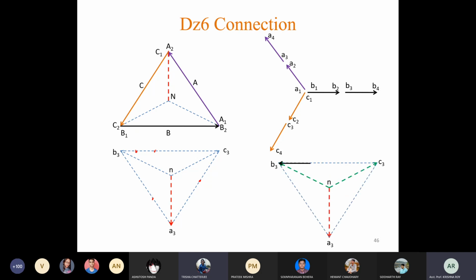First of all, draw B4 B3, A4 A3, and C4 C3. You can see we have reversed the direction of these three phases to get the 180 degree phase shift. Here this phasor is directed from left to right, but this phasor will be directed from right to left. Correct? Yes, sir. This will produce a 180 degree phase shift.